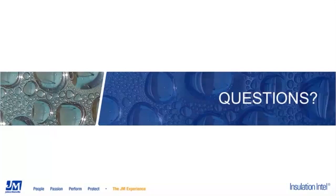For an owner-occupied building, like governments, schools, museums, things like that, if it's the climate-controlled portion of the building, I think fiberglass is probably the better choice. But if it's the non-climate-controlled portions, where you need the extra water resistance to give you system longevity, my personal recommendation, and certainly outdoors, would be to go with a closed cell insulation with a high quality vapor retarder on it.